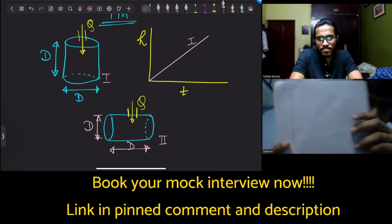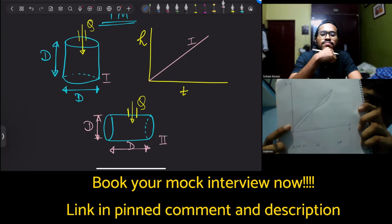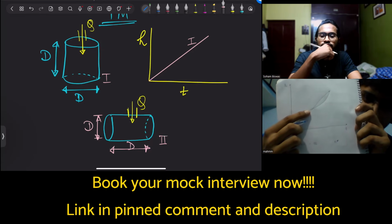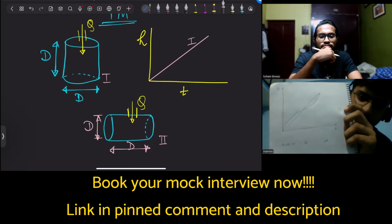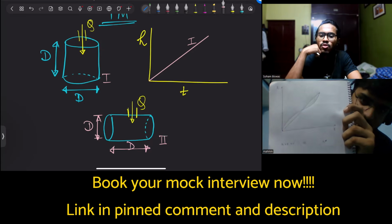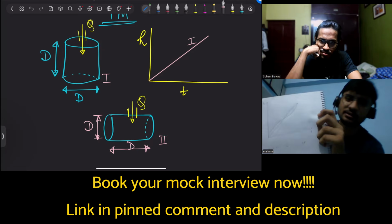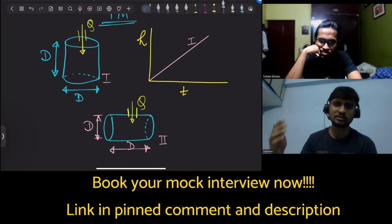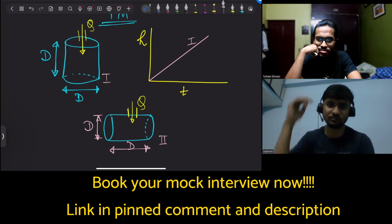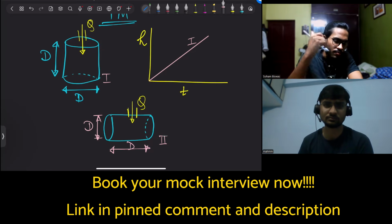It will be like this. At the start, the slope will be maximum and it will be minimum in the middle when the tank is half filled, and then again maximum. For the first half the slope is decreasing. Why? Because area is increasing. As area increases, the increase in height will decrease because the flow rate is constant.